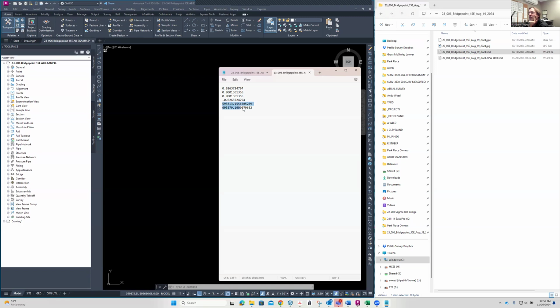These bigger coordinates here, in this instance, this world file is formatted as the top left pixel. And it's not the top left corner of the image, it's the top left center of the pixel. So the pixel is a square, and this is the center of that square right here.